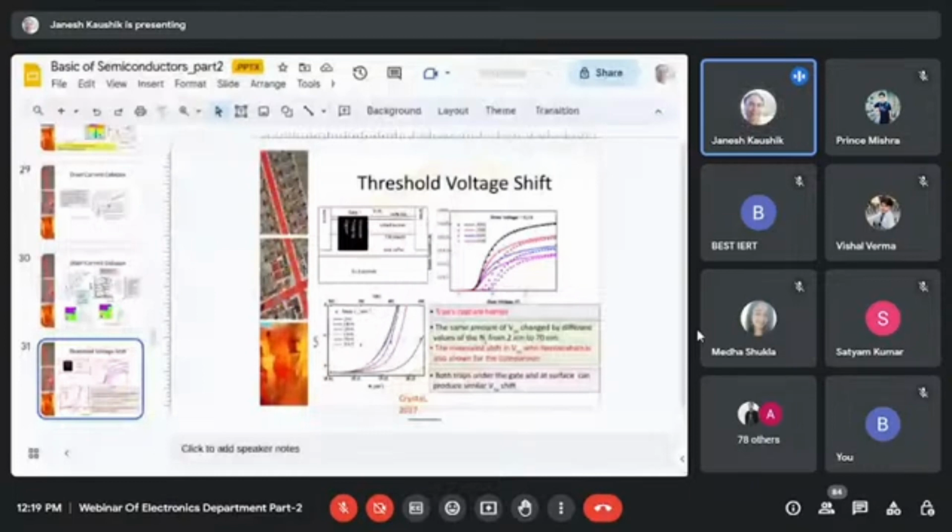and they may give similar values or maybe an additional peak also. But in case of current DLTS, it is not possible to differentiate between an electron and a hole trap. But in case of capacitance, it is clearly possible. In case of current, both signatures are mixed. But again, it's a complementary measurement. We do both.